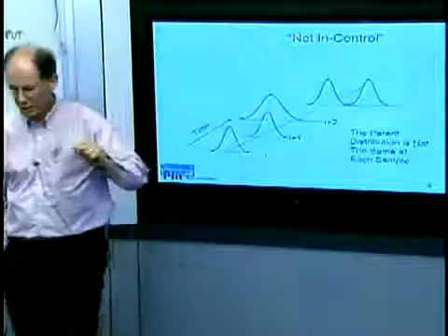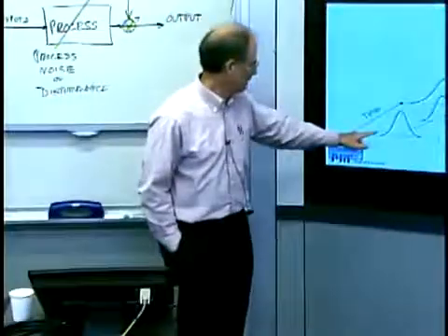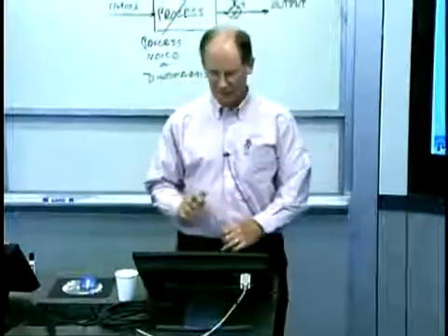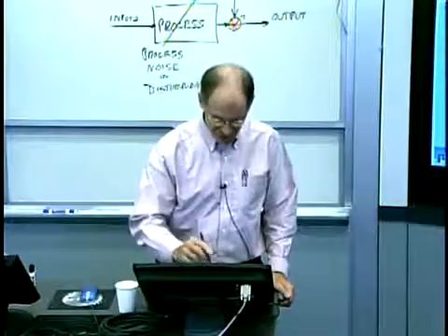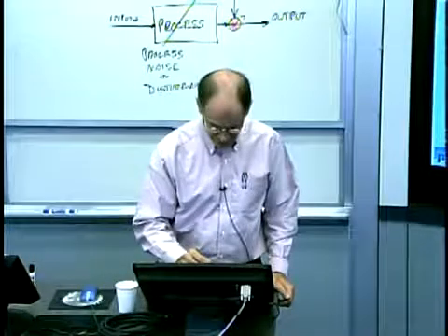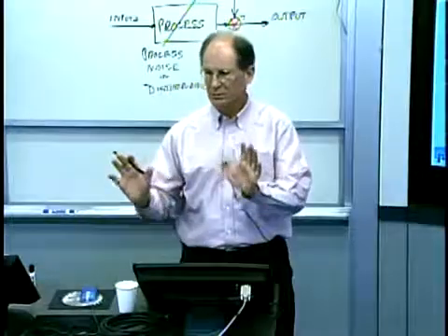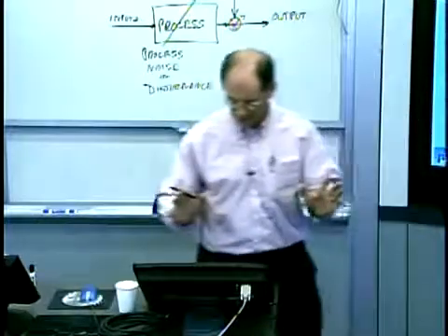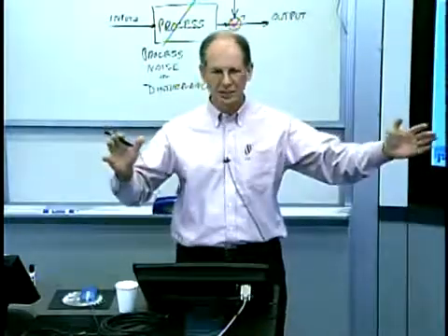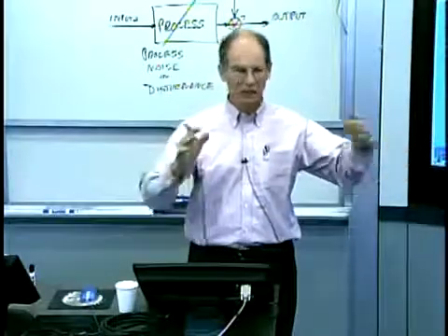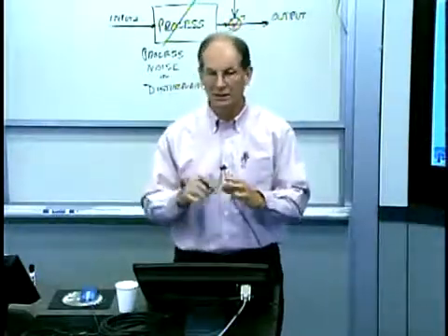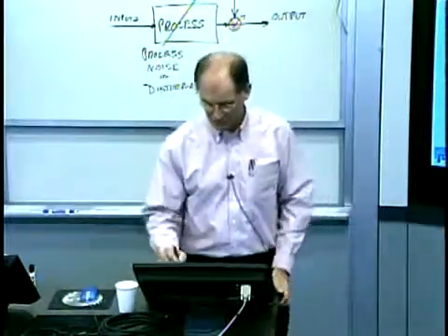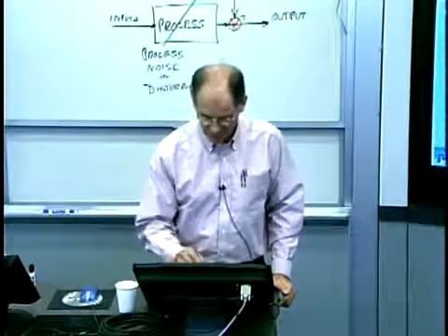What this is basically saying is, well, look what's happening here. In the first two intervals, things looked okay. And then what happened here? Well, obviously, if you can see from the diagram, the underlying random behavior shifted its mean value, and it also got greater variance. So the underlying parent distribution, meaning the underlying random behavior of the process, did not stay the same. It changed at interval 2. And then down here, somewhat later, it got even worse.